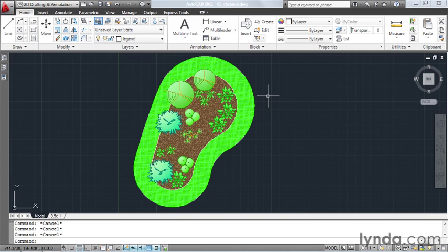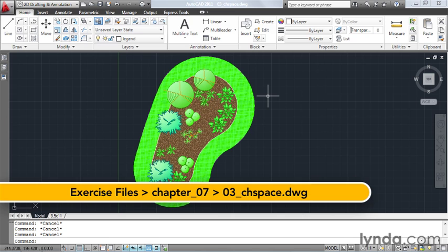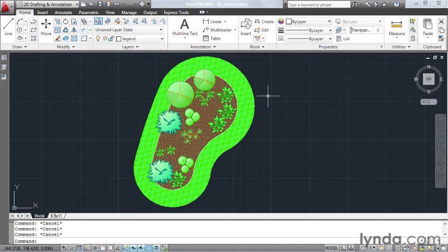One of the easiest ways to describe a design is by using a legend. Legends provide a visual explanation of everything that's seen on a printed sheet. The difficult part about creating a legend is matching the size of the objects between model space and your layout. In this lesson, we'll learn a quick way to create legends using the Change Space tool.